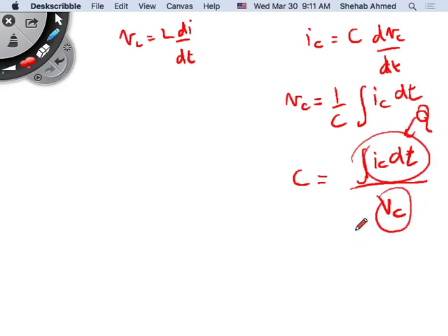So if I know the charge and the voltage between two lines or between any two points in space, then I can calculate the capacitance between the two points. Charge is easy because as long as you have current, you know what charge is deposited on top of the conductor. So we will assume that the conductors carry a charge Q. And in a three-phase system, QA plus QB plus QC will also equal 0 because the currents are balanced, so the charges are balanced in space in a certain area as well, right? So charge is like current in the inductance before.